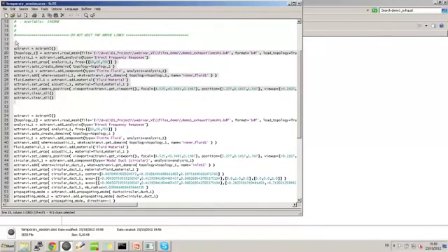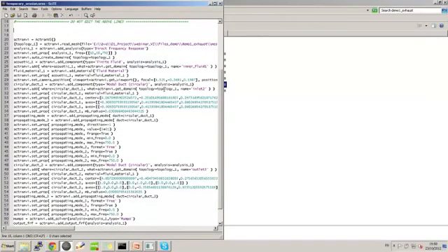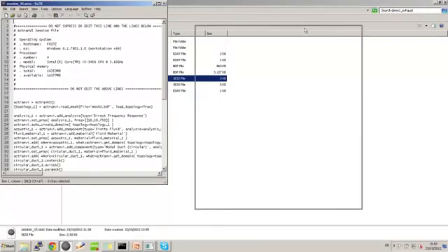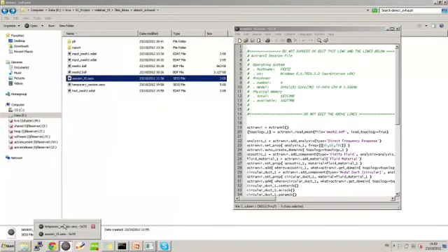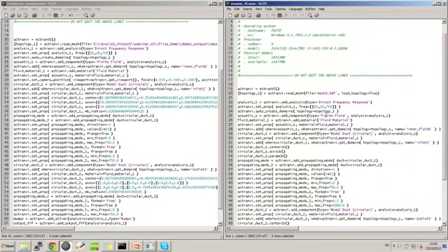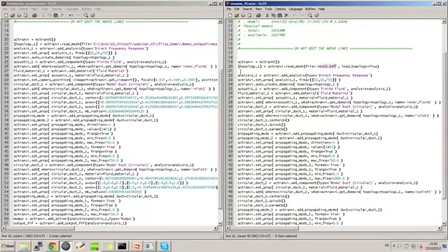What would be interesting is to use this to perform the same type of analysis for different but similar cases, for instance, for Mesh 2. I have already done this in this session. I have performed some small changes that I will show right now. The first change is the fact that I am pointing towards Mesh 2 instead of Mesh 1. The other change is basically almost nothing. The main change I am applying is that the geometrical parameters of the modal duct obviously depend on the mesh type.